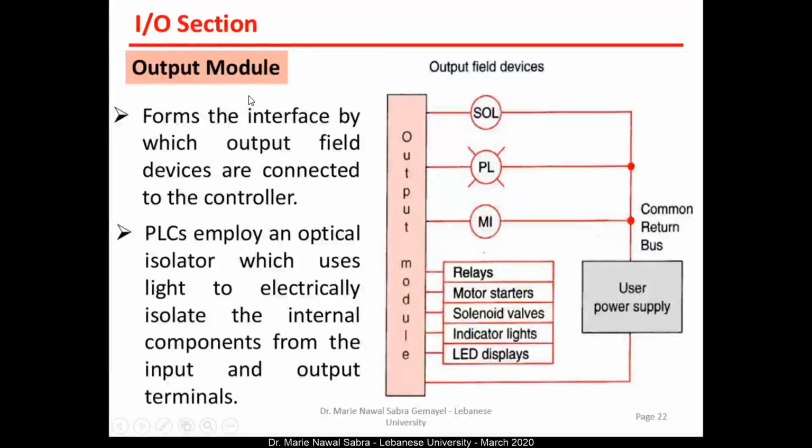The output module. The output module is connected to several real outputs like relays, motor starters, lab displays. We can have lamps, indicator lights. We can have anything that could be controlled, and we can also have values that are read back into the inputs of other PLCs.